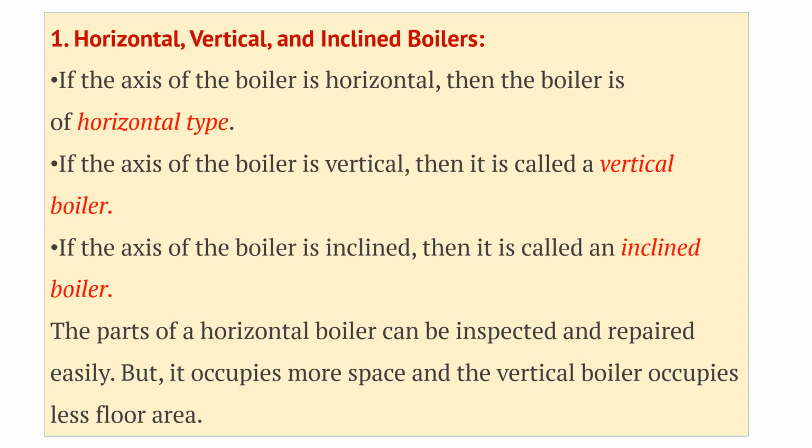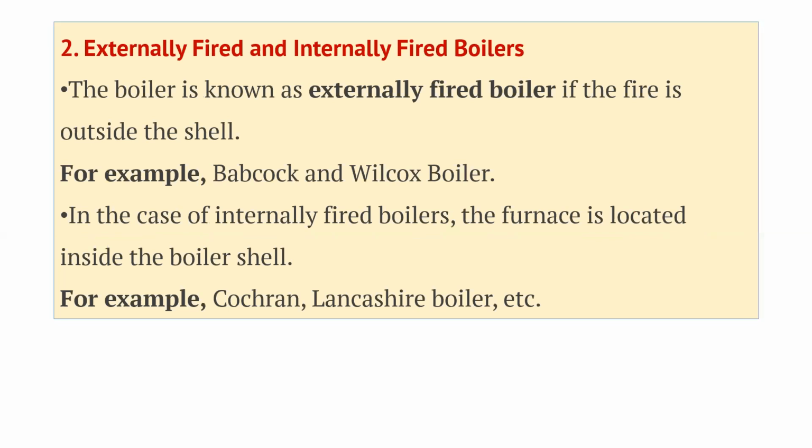Out of all of these, the parts of the horizontal boiler can be inspected and repaired easily. A man can enter the boiler easily in the horizontal boiler, but there are some difficulties in other varieties. And the second parameter to classify boilers is externally fired and internally fired.